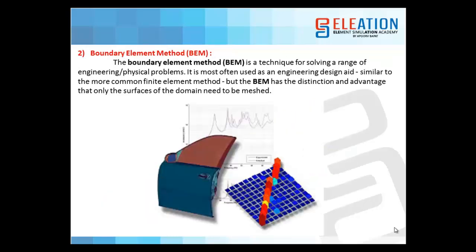Then the next approach in numerical methods is the boundary element method, which is a technique for solving a range of engineering or physical problems. It is most often used as an engineering design aid, similar to the more common finite element method, but the boundary element method has the distinction and advantage that only the surface of the domain needs to be meshed. Mainly it is used for NVH, that is noise, vibration and harshness problems.